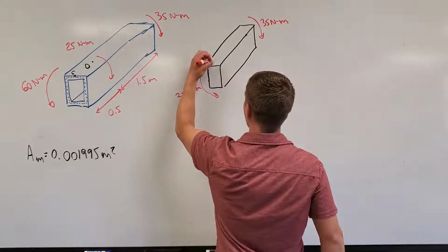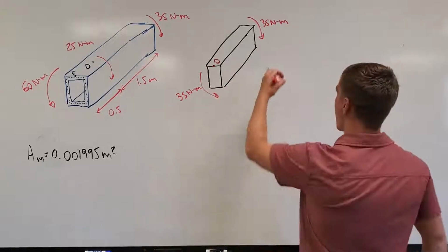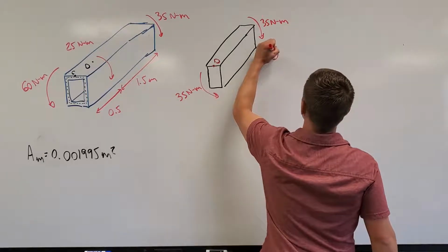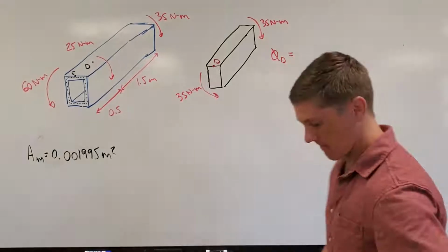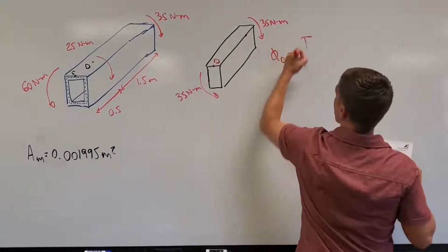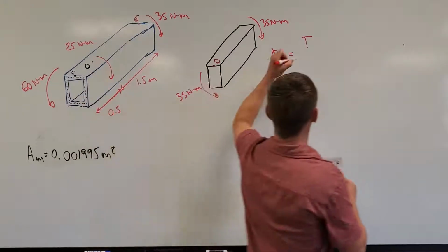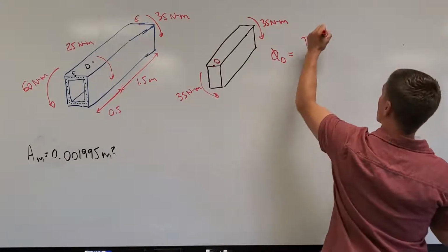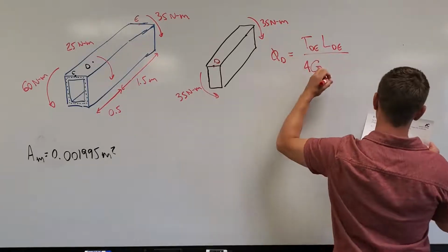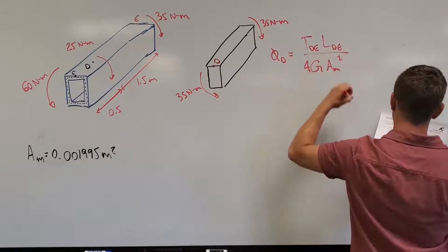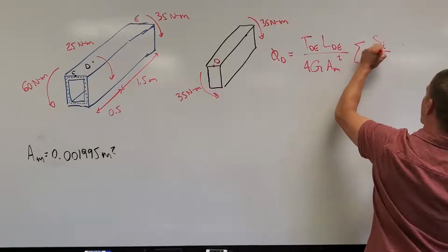So once again, I made our cut here at point D. So I'm going to say that my rotation of the shaft at point D, phi sub D, is then going to be equal to our torque between D and E, and once again this was location E at the wall, times the length between D and E, divided by 4 times the modulus of rigidity times our mean area squared, times the sum of our arc length over our thickness.